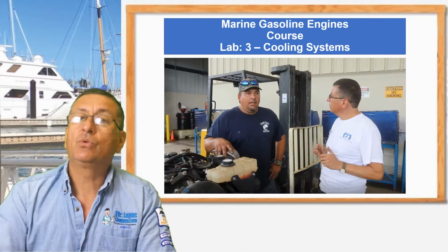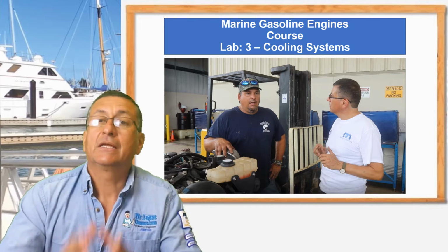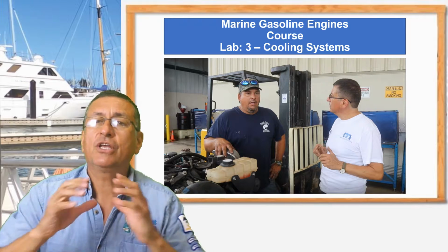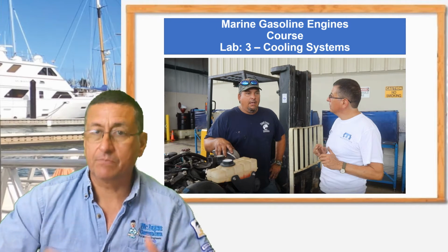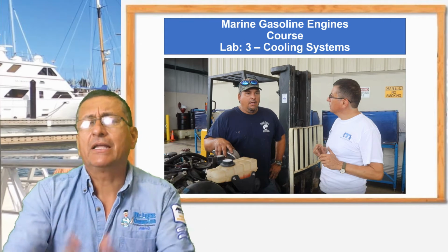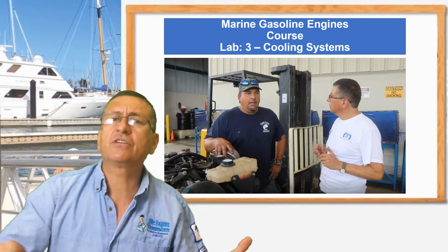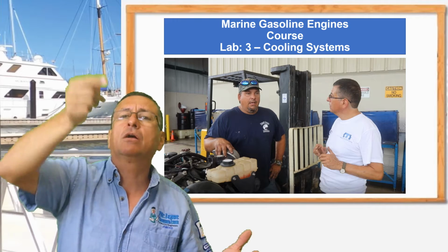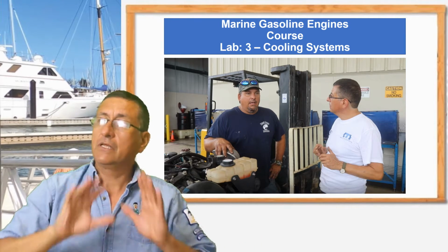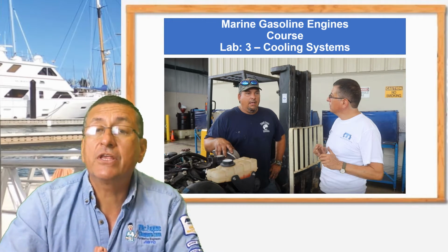Today we are going to continue in our class of marine gasoline engines. This is laboratory number 3, and in this laboratory we are going to analyze the cooling system for inboard engines and outboards. Remember, in the outboard engines, the cooling system is a raw water system. It's raw water circulating to the block and the head and returning outside through the middle of the propeller. This is for outboards. For inboards, we have a different type of refrigeration.